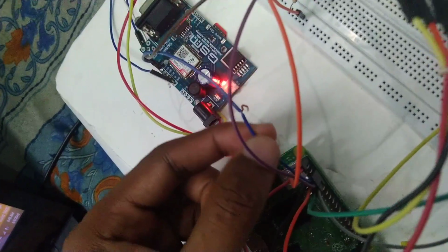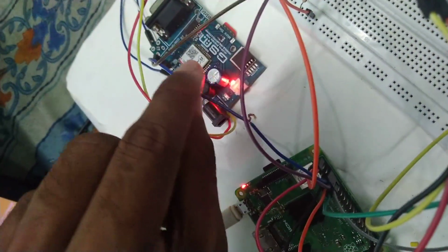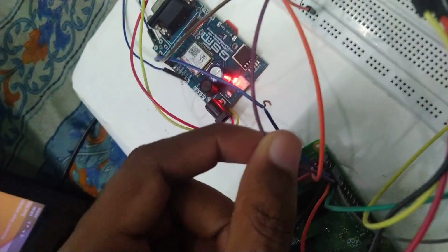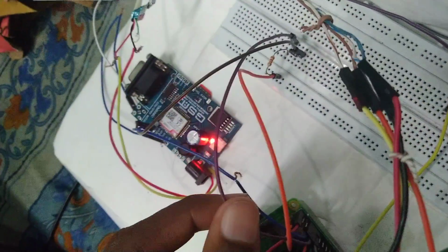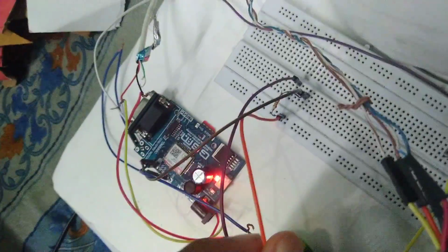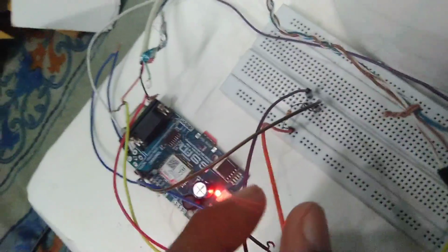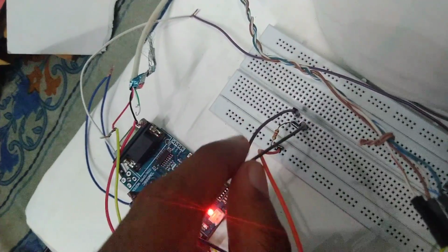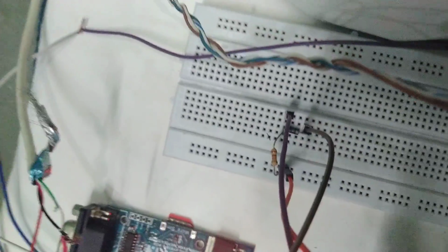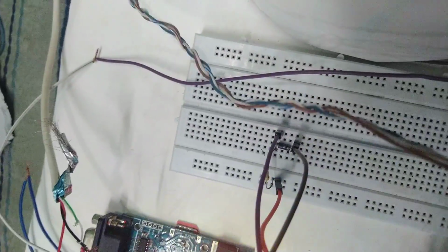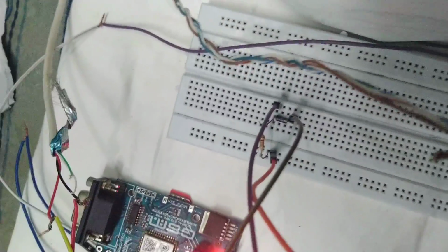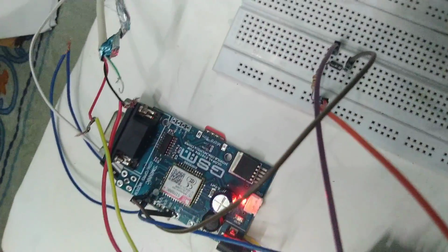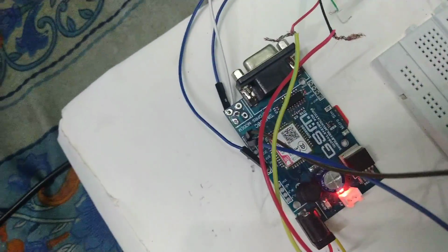As you can see, this TxD is directly connected to the RxD of the GSM, and this RxD is not directly connected, but it is connected with a voltage of 3.3 V input, and with a diode in between, and the output is from here. As you can see, this is the connection. So we are giving 3.3 volt with one resistance and with the input and with one diode, so that there is no reverse bias current from the GSM. Okay, so as you can see, we have connected it here to the TxD port, and the ground can be connected to any port of the Raspberry Pi.